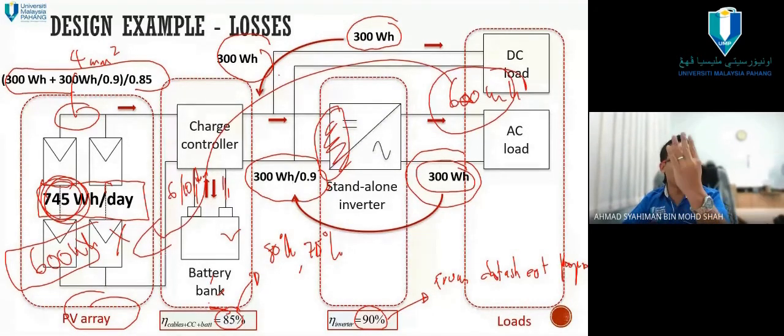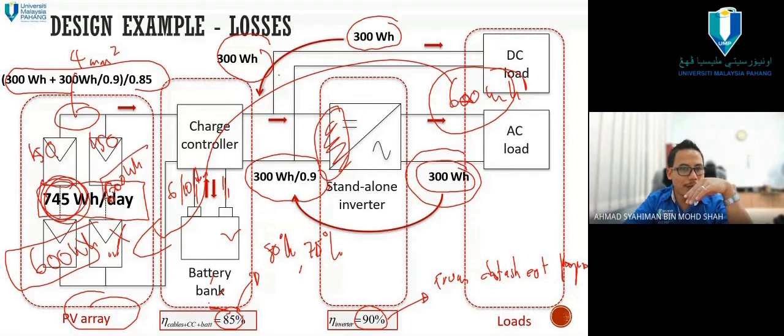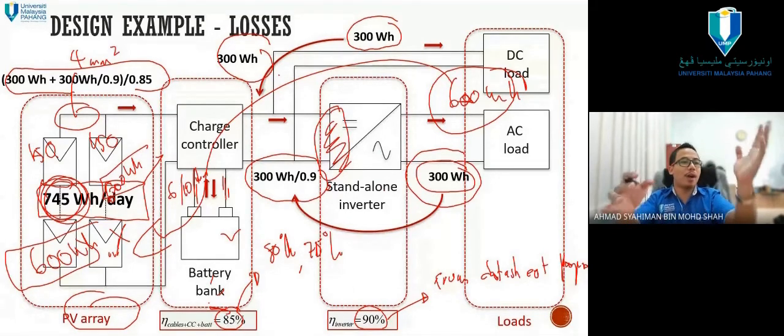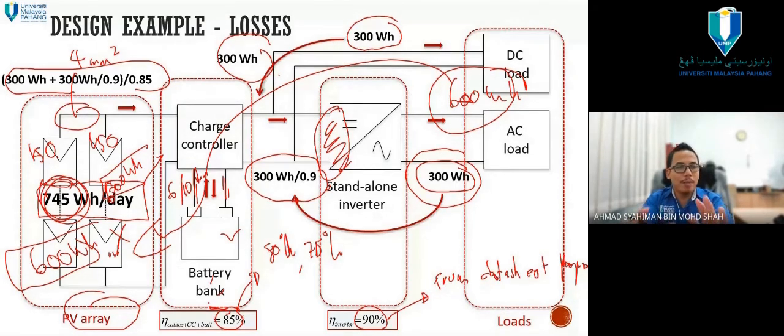600 watt hour means what? Buy only 4 solar modules of 150, for example. I'm saying per day, but let's say per hour, to be more critical. They buy 4 of 150 and get 600 watt hour, producing 100 watt hour in an hour. But actually, after considering the loss, the load actually uses 745 watt hour in 1 hour, for example. So maybe after 40 minutes everything is off, the lights don't work. They say what's broken, the battery has no brand, it's a scam. That kind of thing. It starts to shut down. Why? This is already wrong.